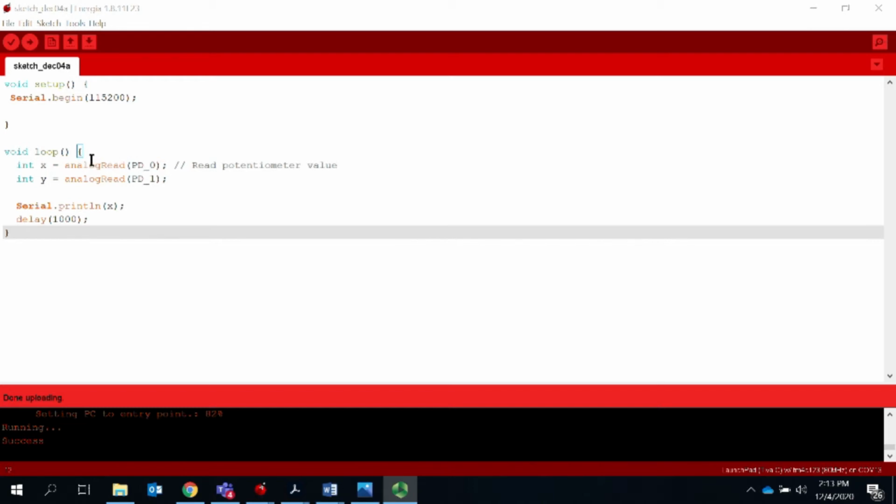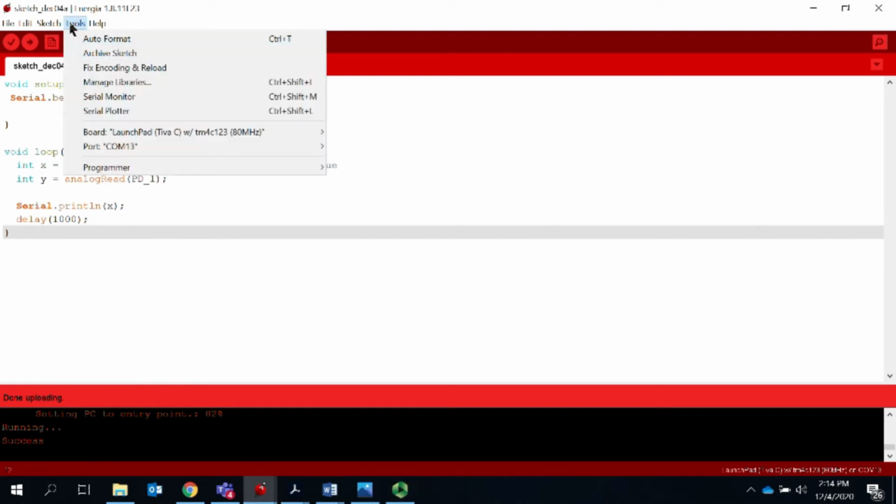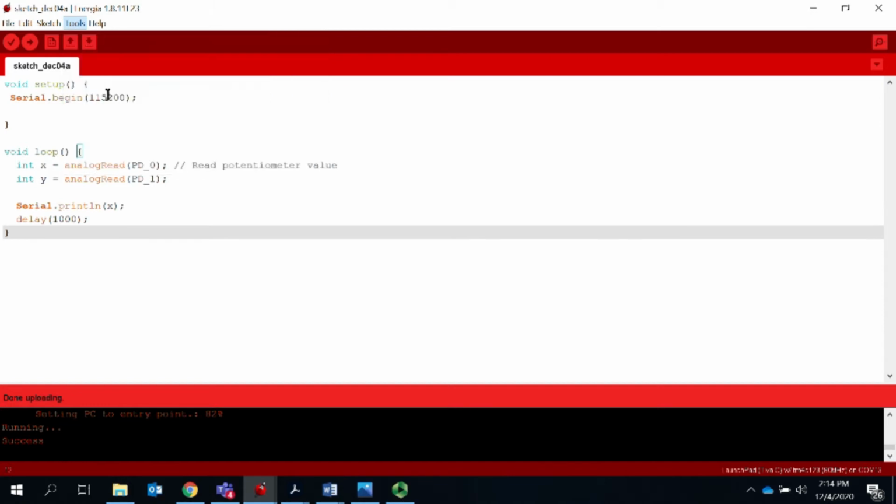And then the microcontroller converts that voltage, which is between 0 and 3.3, to a digital value, which should be between 0 and 4096, which is 2 to the power of 12. So we read these numbers and have them inside these two variables, then we simply print that value. Let's start with pin X of the joystick, and here we just use a serial print to see the value in our monitor. So let's go to Tools and Serial Monitor.